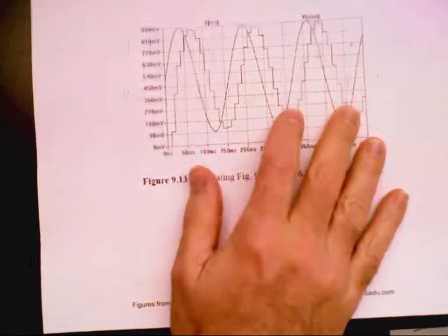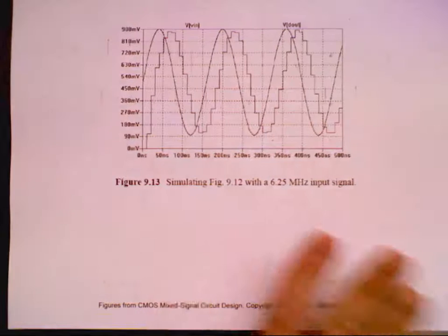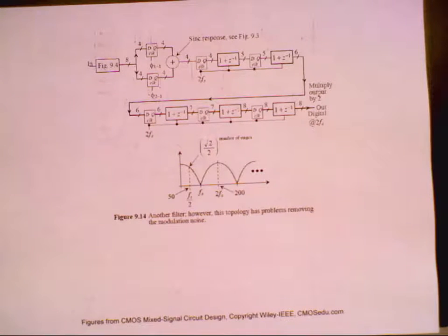And so here's what happens when we redesign the filter without as much attenuation. And gee, it looks better. It's not as attenuated. Then we say, okay, what happens if we don't decimate right at the front? Instead, we're going to ping pong back and forth. The whole point of this figure is that when you're doing designs in hardware, it's really easy to do something and not realize you're manipulating or filtering your signal with your DSP.